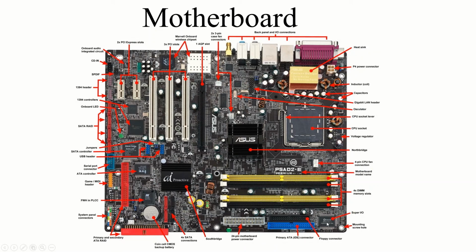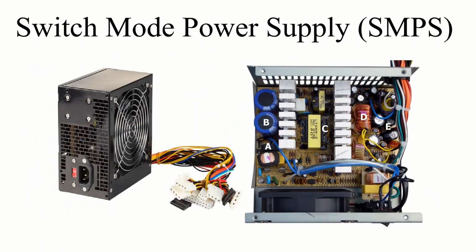After that we can also check the RAM slots. Sometimes power is coming but it is not working because of an issue with the RAM, or there is dust in the RAM slots. We can remove the RAM, clean the slot, and put it in again. Sometimes the issue comes from the SMPS power cable, the Molex or SATA cable, and we need to change this cable for the hard disk or another device.